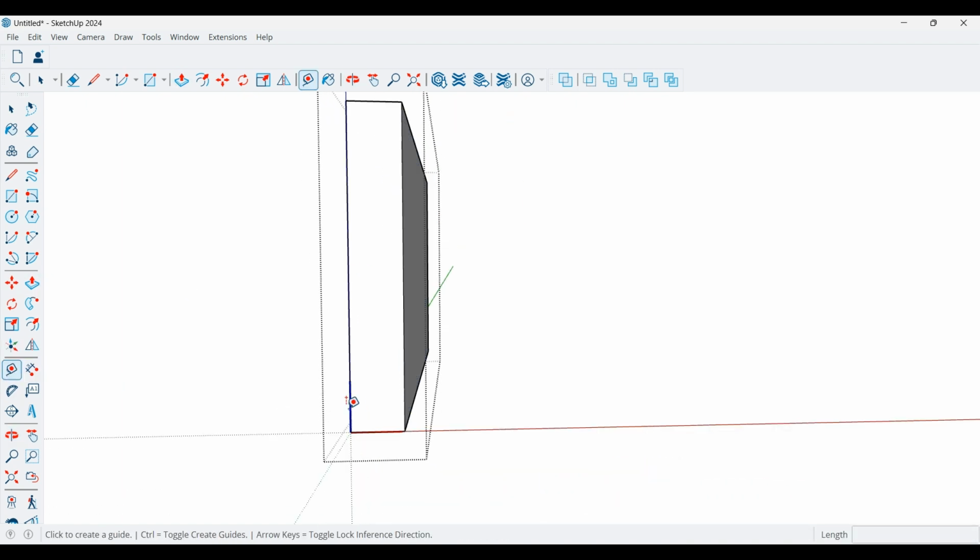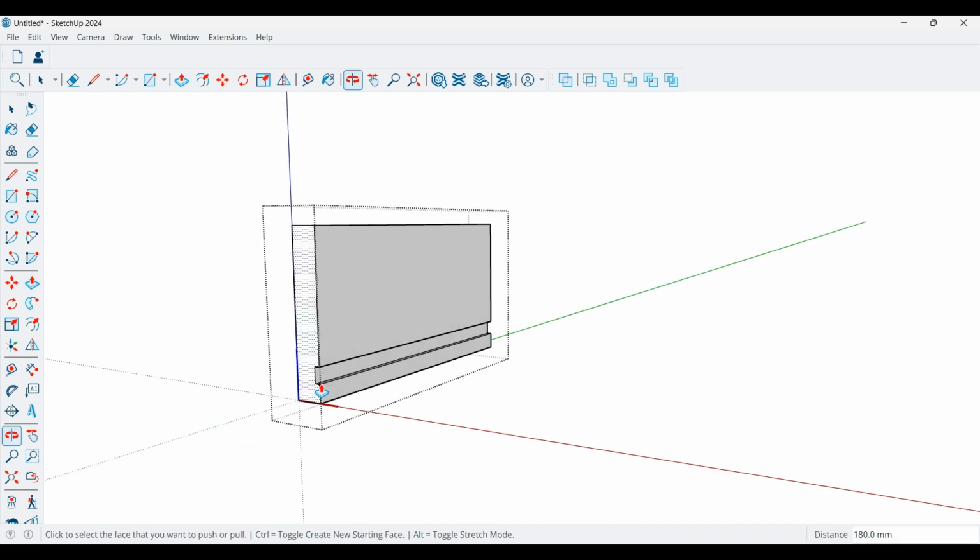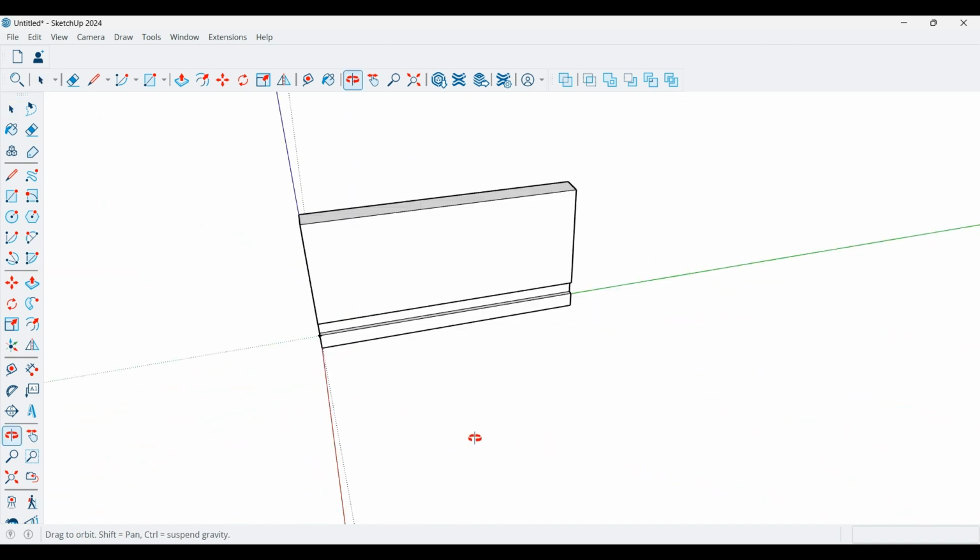We then get our tape measure tool and click up and drag a line up for 10 millimeters. On that guide point, put a rectangle that is 3, 9 millimeters. Okay, so we see I've got our bounding box around us, which is good. We're allowed to edit it. We're going to double click on that till we get the dotted box, get the push pull tool, and drag that across, hover over that back edge so it cuts all the way through. Okay, looking good. Now we can hit spacebar or get the select tool and select in white space so it deselects it. That's what we want.